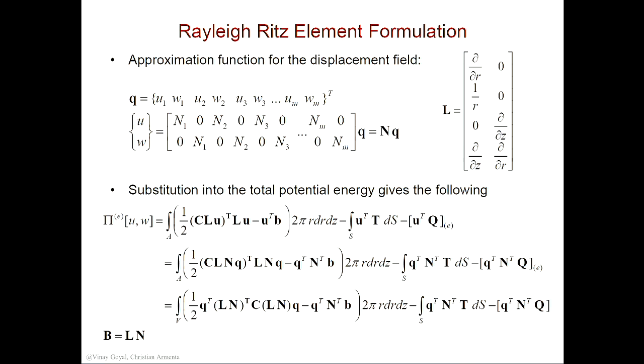So then what I'll do, I'll substitute these relationships. For example, we know that stress is the constitutive law times strain. You agree? That's what that used to be. It was a stress here, right? So C times epsilon, and we already said that strain is L times U. This L bold times the displacement field. Okay, so that's that. And this used to be strain bold. I'm going to make it LU bold so that is strain. So then I have stress times strain. Okay, and the rest stays the same. I'm going to leave everything else the same.